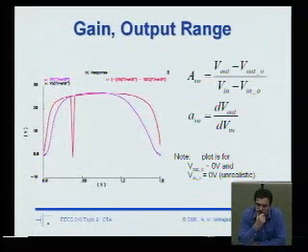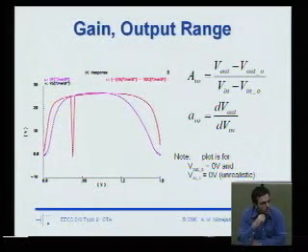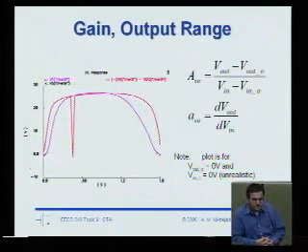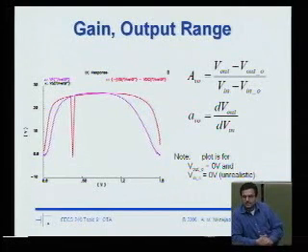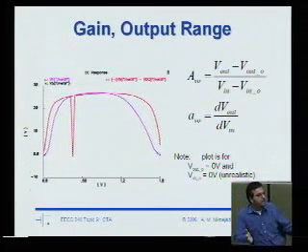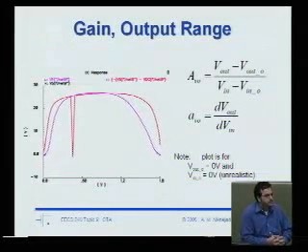But, so coming back, which is more valid, the large signal gain or the small signal gain? Okay, the large one. Why? Well, first of all, notice that Mr. Murphy is absent from this graph, right? Murphy's law always tells us that things are always worse than you think they are, right? And here, all of a sudden, we realize that large signal gain is what we care about, and boy, we get more output range with large signal gain. So that's actually a good thing. One of those times where what you care about actually is better.